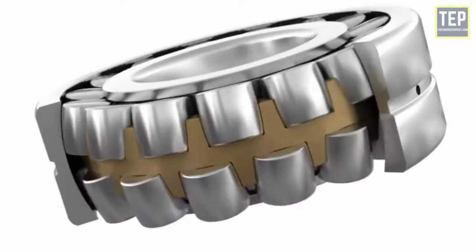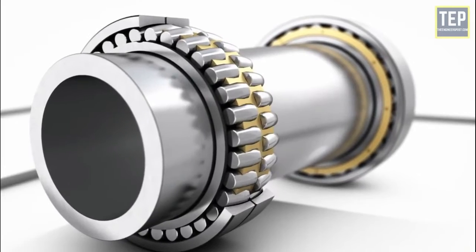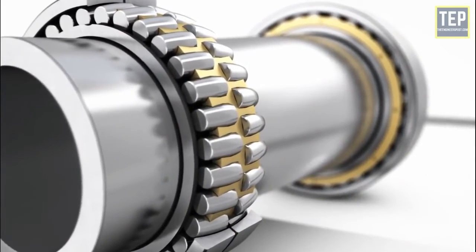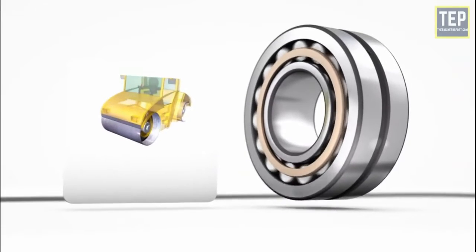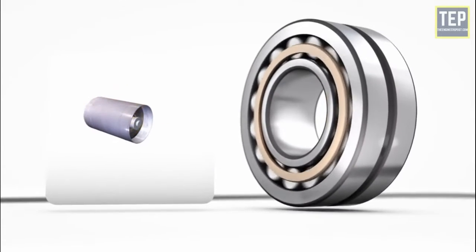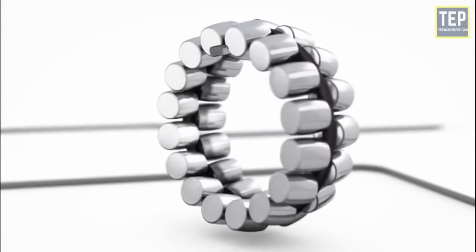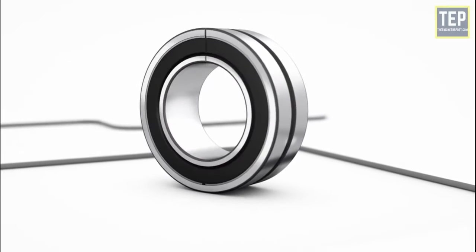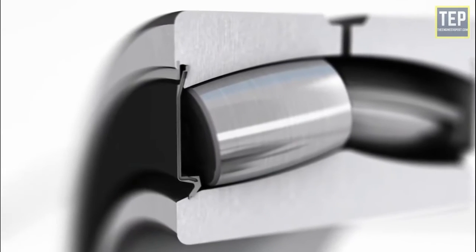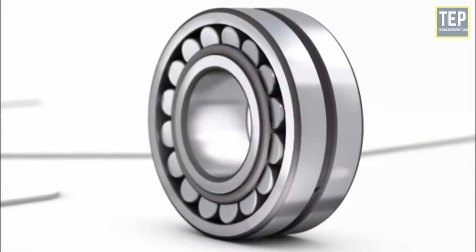Roller bearings maintain accurate alignment of every part over a long period of time and can carry heavy momentary load. This renders them suitable for machinery which requires frequent starts and stops. Rollers make line contact with their races, while balls make point contact. It has a higher load carrying capacity. Roller bearings contain cylindrical rolling elements instead of balls as load carriers between the races.